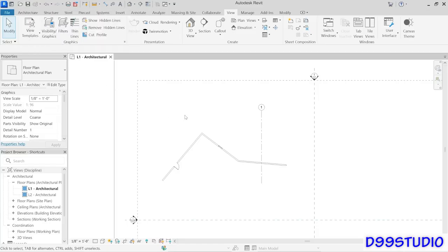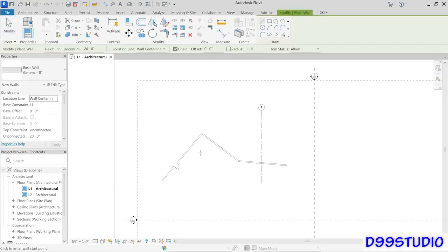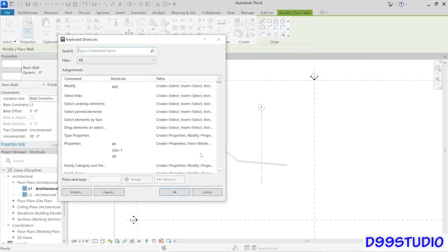Now, let me just make one other comment about the shortcuts, the Revit ones that use two letters. It's pretty important that you just type the two letters. Don't press the enter key. Sometimes there's an instinct to follow the two letters with the enter key. And if you do that in Revit, you're going to get unexpected results. For example, let's say I was trying to draw a wall. So I type WA, but then I press enter. And suddenly the keyboard shortcuts command appears. And I may be wondering what just happened.